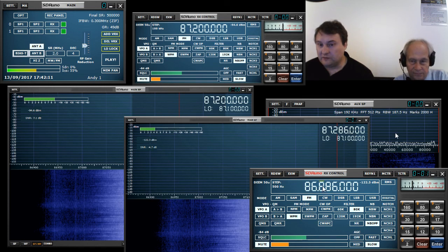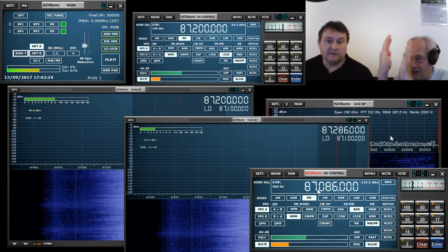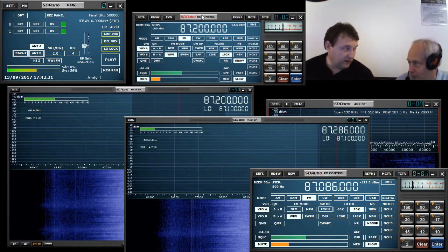I don't know if you can hopefully see that in the RX control window, it's allowing me to only go within the LO frequency plus or minus 250 kilohertz. You're boxed into a slot of spectrum dictated by whatever is set in the main VRX0.